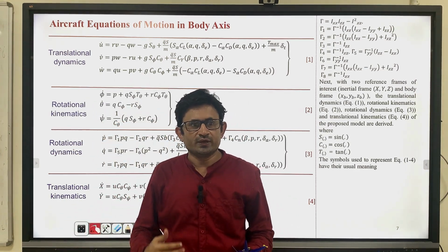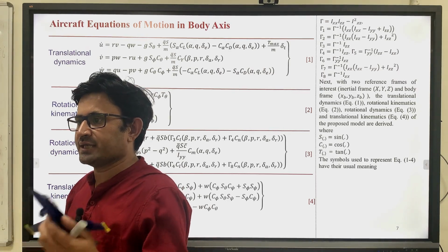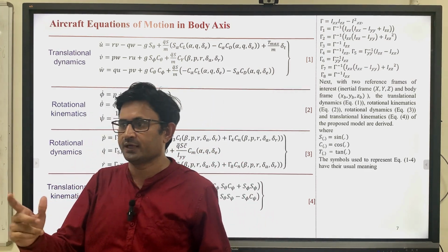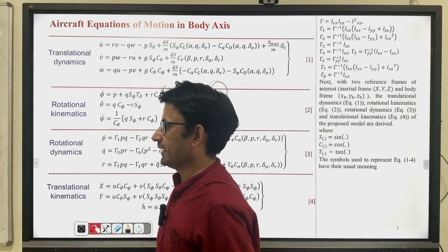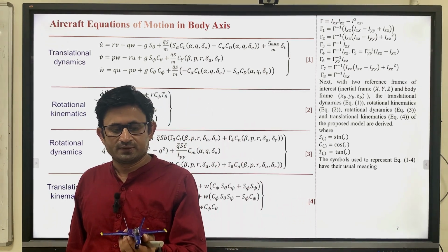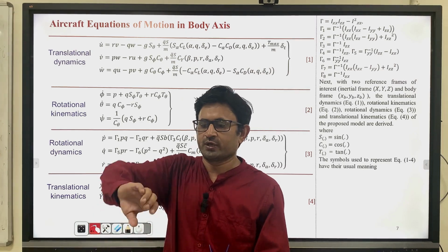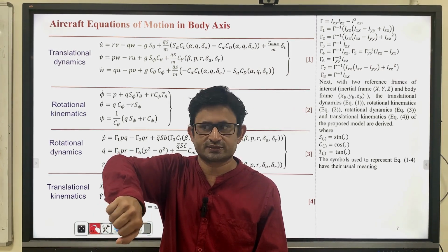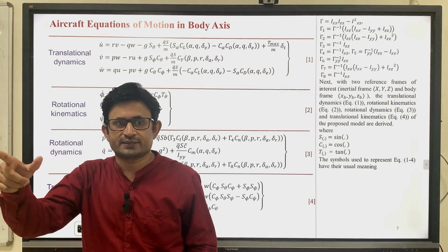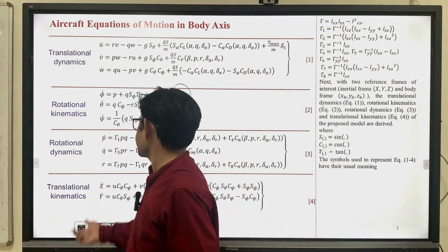But since we have to take the information from the body, because actually the body is moving, and as an observer we have to sit in the inertial frame and measure every quantity. That is why we have done the 3-2-1 rotation, and that is this part. And when you rotate with some angle, for example when you go from the body to inertial, you can rotate with some rate, phi dot, theta dot, psi dot. So that means you can establish the relation between body rates and Euler rates, phi dot, theta dot, psi dot, and P, Q, R. So that I have given to you.